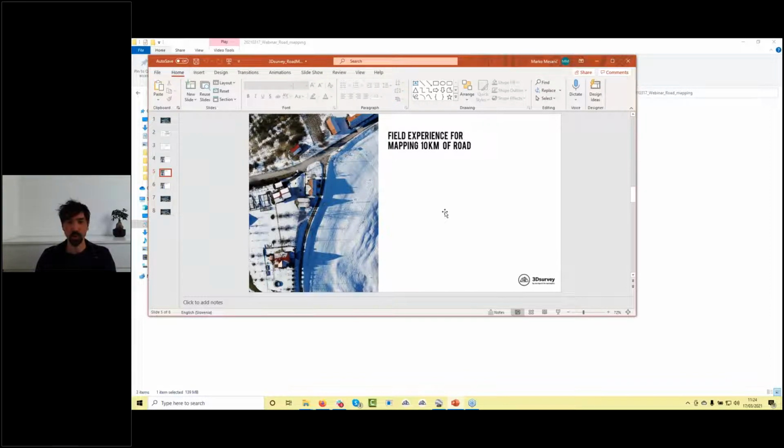Okay, I'm not sure if you recognized, we had turned off the obstacle avoidance sensors. This was because we had a lot of issues a long time ago with the low sun, and if the drone flew directly toward the sun, the sensors figured it was some kind of obstacle, and the drone stopped, noticing there was something, but the drone was at 80 meters. So after a few projects, we figured out that the sun is a problem.